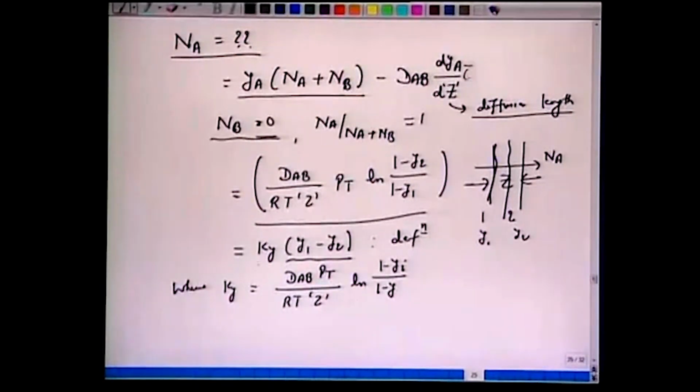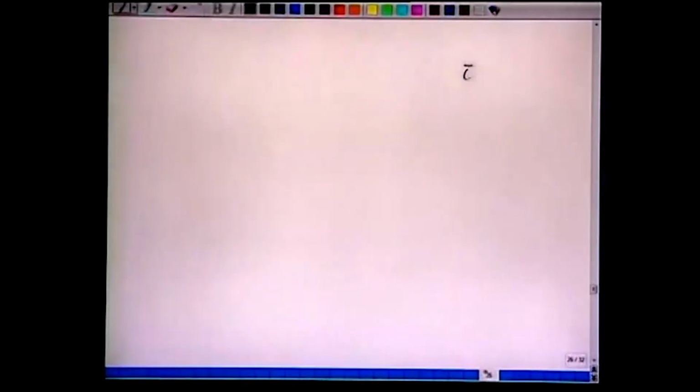Of course, this is a very general expression, but in our case we have also said earlier that we calculate ky from Reynolds number and Schmidt number, or from Sherwood number, or from some correlations. Which means now we go back and we write G dy over (1 minus y). So, this was the change in the gas phase, and this equates to the flux, which is ky (y minus yi). So, that is what we have, y1 minus y2, we have the diffusion length y1 and y2.